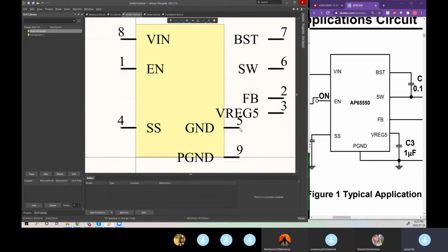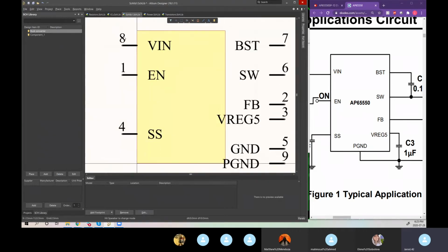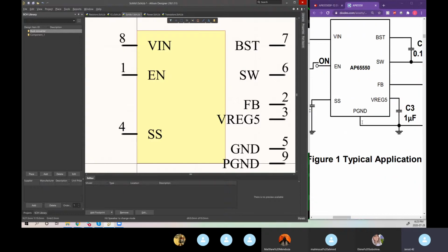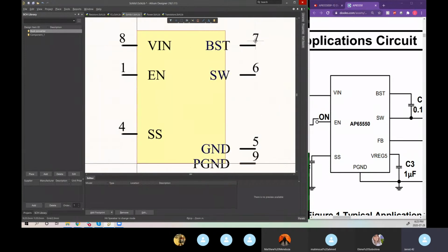So they shift their pins around. So you can see in our actual schematic, we don't have to follow going 1, 2, 3, 4 up to 8 all the way around numerically like it would be on the physical device, but we can lay it out in whatever manner we deem cleanest or best for us.